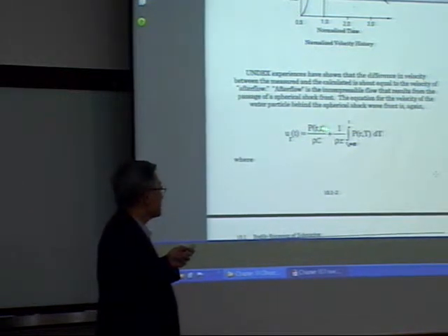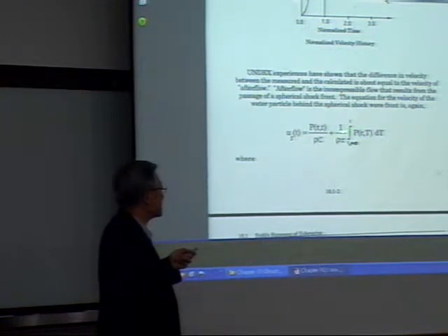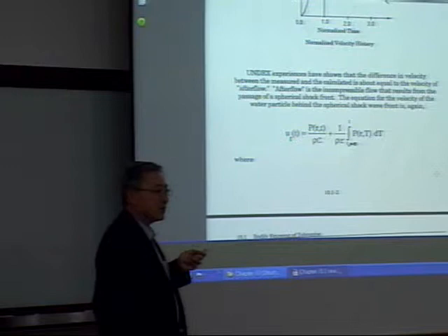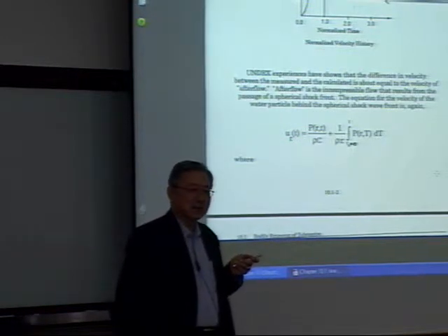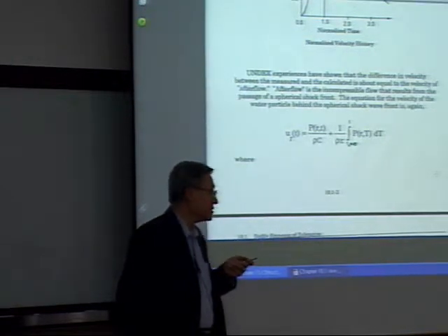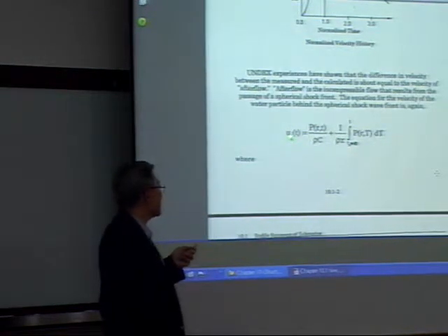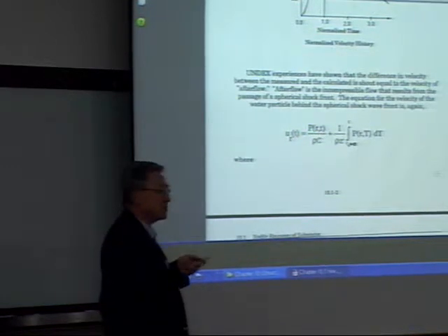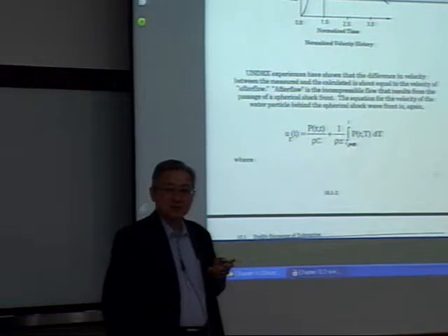This is a relation between the shock pressure and fluid particle velocity. Treat the ship or submarine as a particle because it's rigid, to compute the bodily response. So here, if you don't have a second term, this is exactly for what wave? Plane wave, right? P is equal to rho c u. Without the second term, u is equal to P over rho c, right?